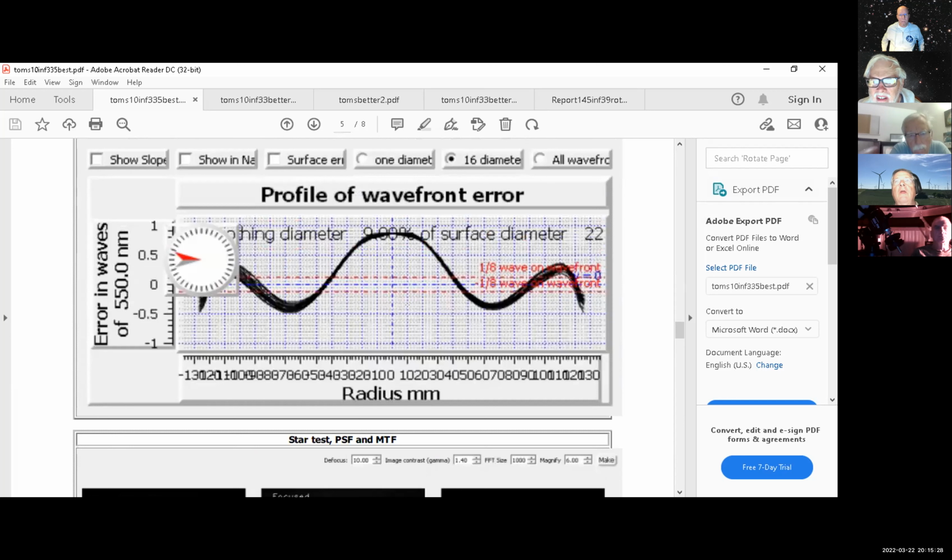But I have a feeling what I can do here, and I'll do it like the local mirror maker here does on the big mirrors. I'll start in from the outer edge. It looks like the 80% point is too high here. And so if I can work on that, get that down a little bit, possibly with a small lap, and then get that to be better, then I'll start thinking about doing the inside here, which is less important.